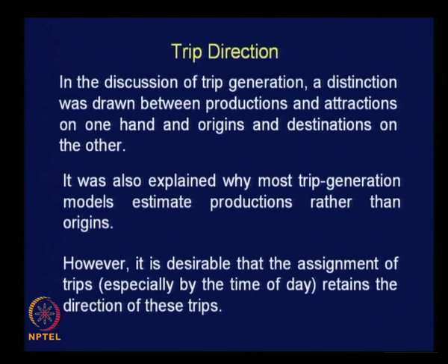However, it is desirable that assignment of trips, especially by the time of day, retains the direction of these trips. It is obvious, that is what we discussed about. While you assign traffic, the direction of movement has to be retained, which is possible by converting your PA matrix into OD matrix. That is why we discussed about conversion of PA matrix into OD matrix only for this particular purpose.